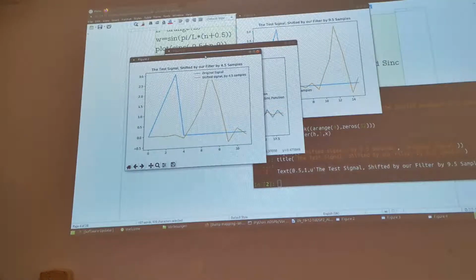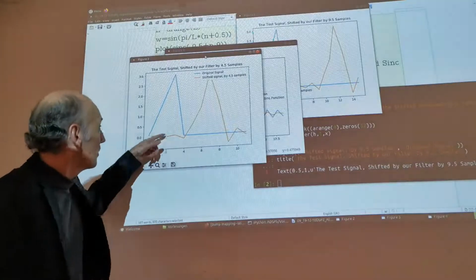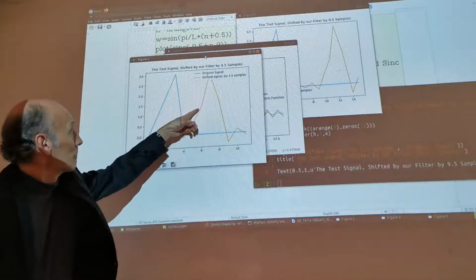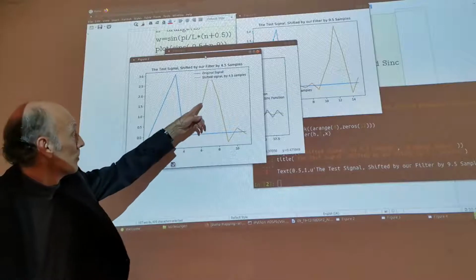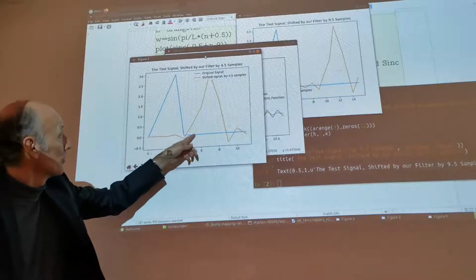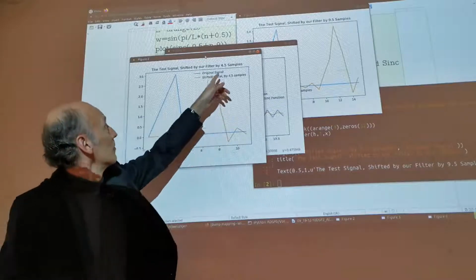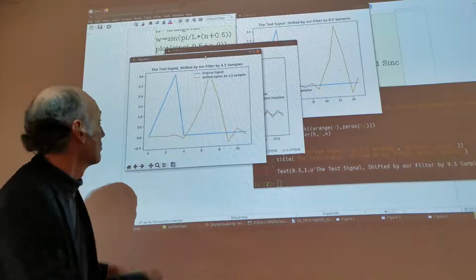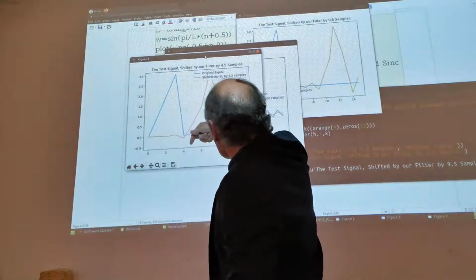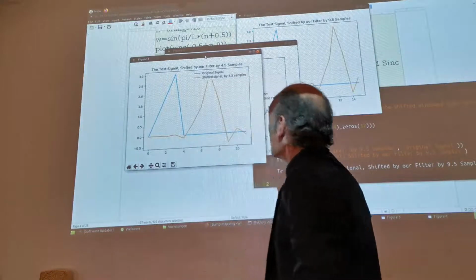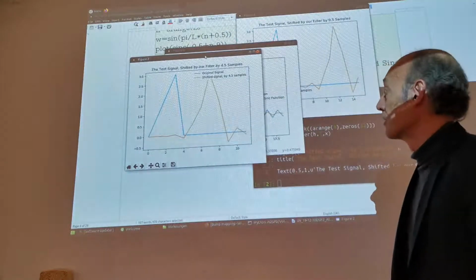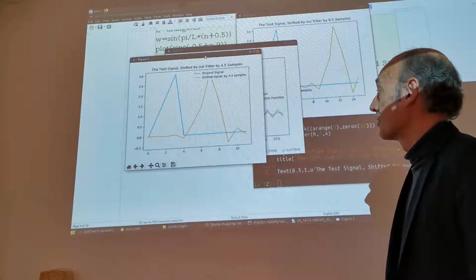If you just have one sinusoid, then it's not so easy to see artifacts. So when you extrapolate, you cross the x-axis at about 4.5 samples, which is the desired delay.